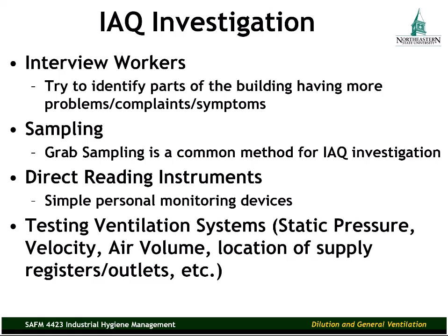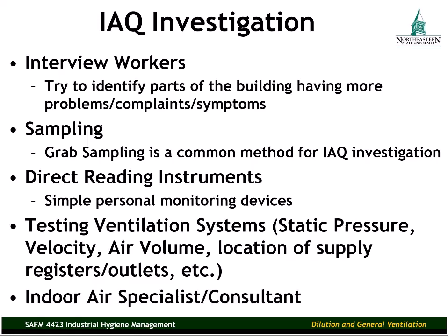After you've gone through these 4 steps, if you still aren't able to identify and correct the problem, maybe you need to bring in a specialist, a consultant. And don't be too proud to ask for help. Bring in an indoor air specialist to take some additional readings, to look more specifically at certain components of the ventilation system. But again, if you have indoor air quality problems, headaches, nausea, complaints from workers, we need to stay on the mystery until the mystery's solved and the problem's corrected.